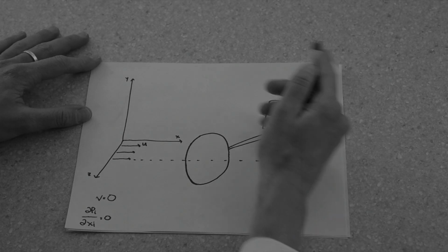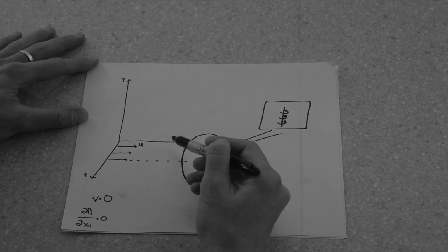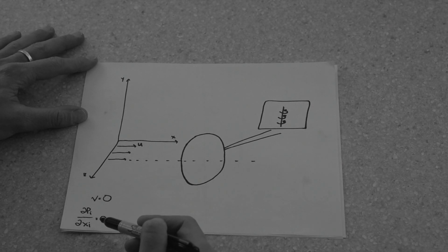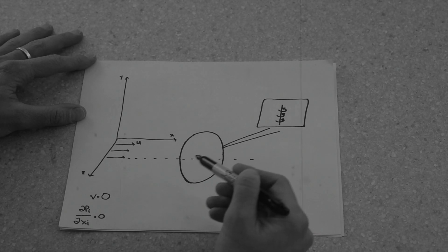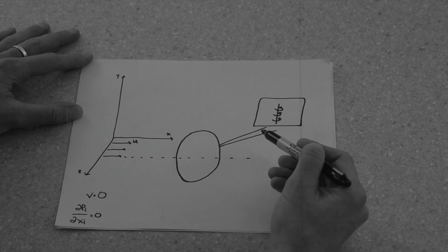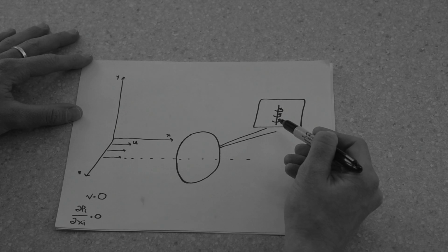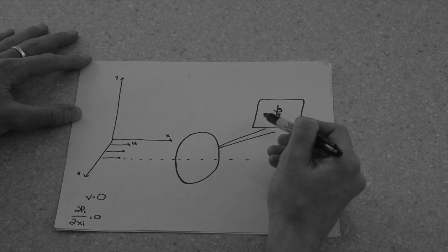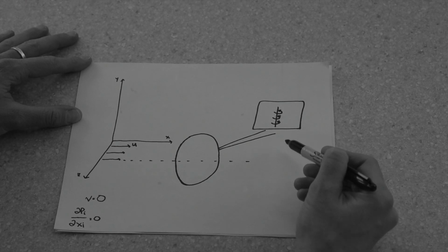Now, consider an infinite incompressible media that is at a steady, uniform flow in the x direction with no applied pressure gradient and no viscous effects. If we were to spontaneously generate a vortex ring that is very large, and consider a very small portion of that vortex ring, it would appear as a vertical vortex tube that rotates at a constant speed and would travel through the media in the x direction forever.